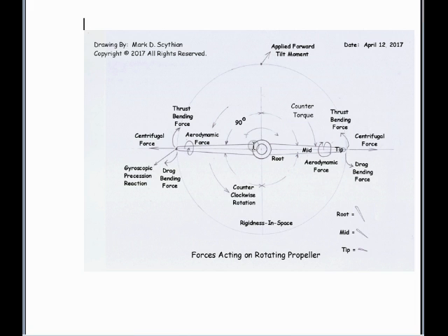So the pilot, knowing the airplane, the certain equipment they're working with and its limitations, would know that if they were going to right rudder without coordinating the ailerons on the bank, they were just going to hit a little right rudder to line up somewhere. They would get a little bit of a down moment, and they would just pull back on the yoke a little bit to induce a little positive pitch to cancel that down moment. So you can see the logic behind it.